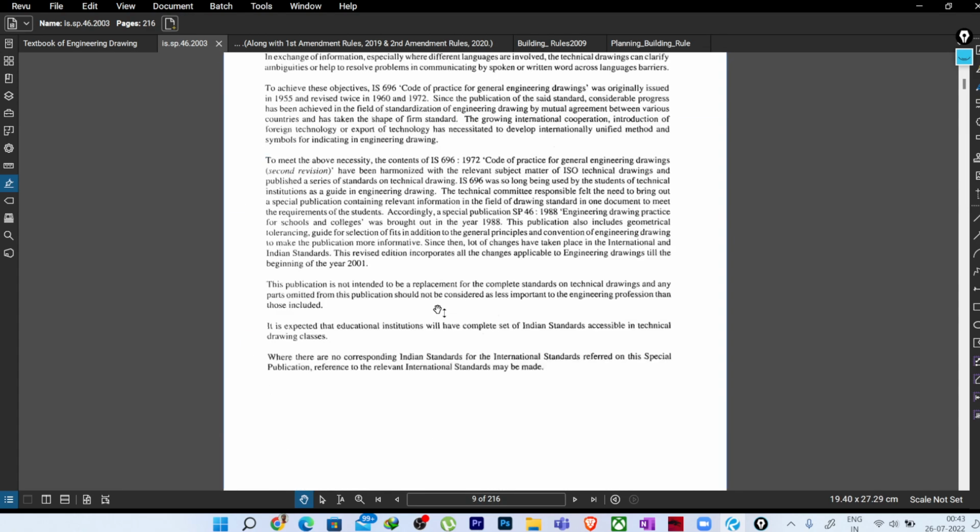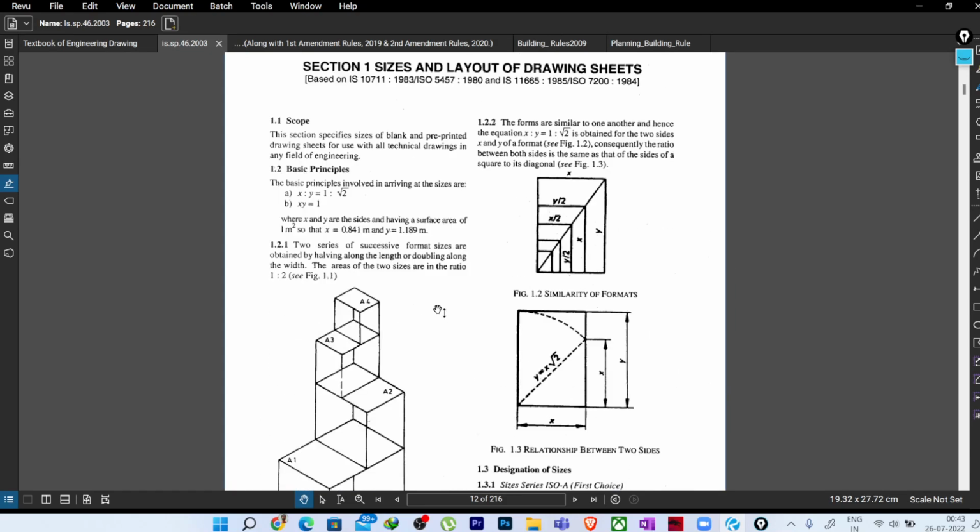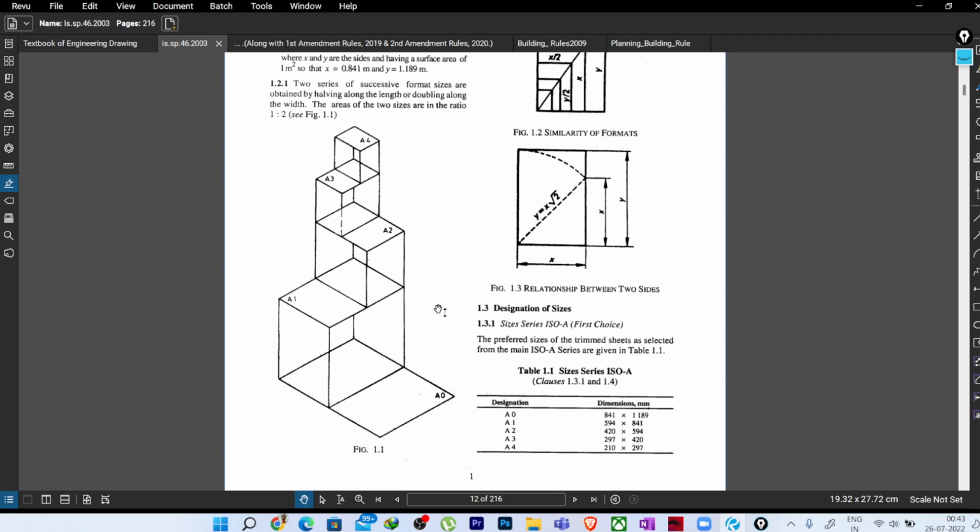So here, at the very beginning, what I will show you is the paper sizes. Why are paper sizes important? Because this is where you will be putting your drawings, and it will go to the site through these papers. So in whichever paper you need to print the drawing, accordingly you need to maintain every single thing in the drawing, starting from the line thickness, the text height, the text sizes, the dimension sizes.